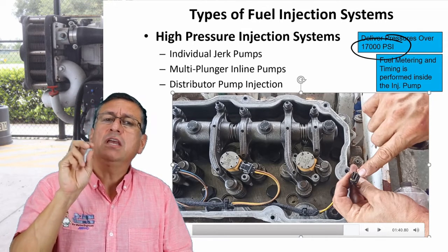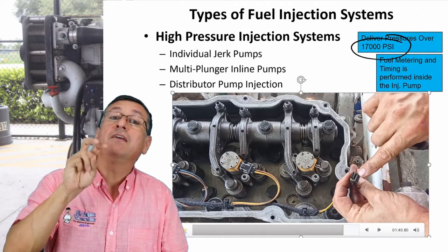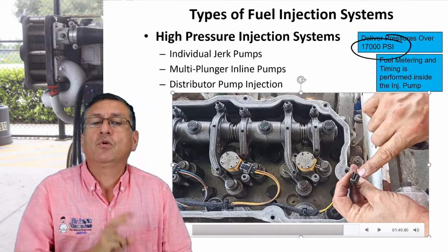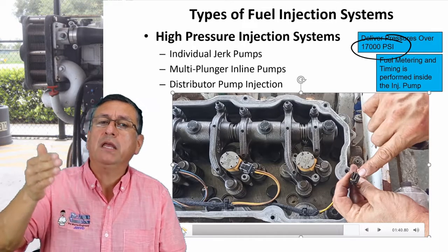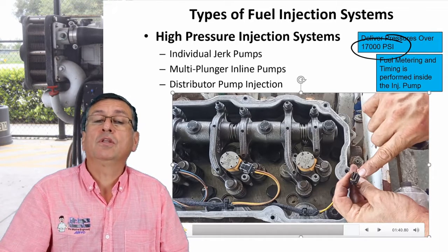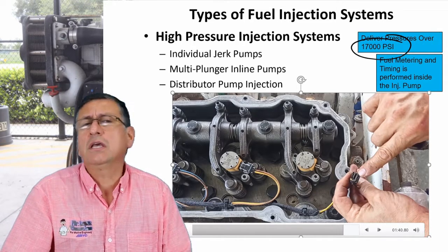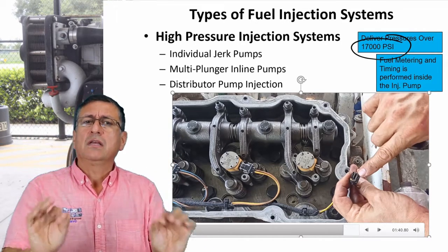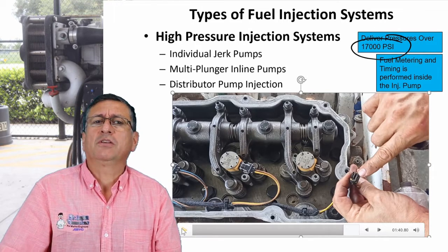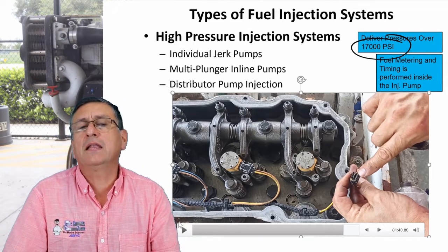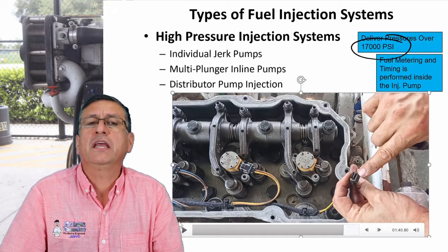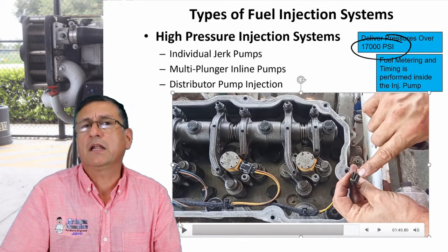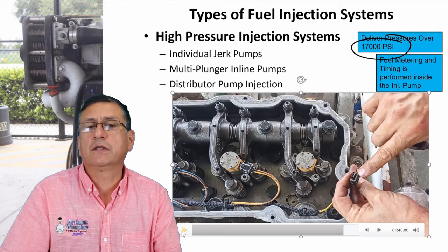With 5 volts DC, you can verify if the solenoid of the injector opened properly. If not, you can replace the solenoid. I am going to explain in this episode the procedure to replace the solenoid. In some cases it's possible. If not, you can send the injector to a machine shop specialized in injectors, and the machine shop returns the injector properly calibrated. Normally they replace the solenoid.